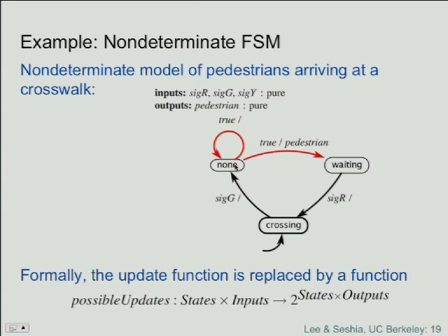Yes, question? So does that mean when you're in non-state, with no condition attached, it just stays yellow? Is that what's the question? Well, so I think what you're asking is how would we fix the design defect that we identified, right? Which is that if a pedestrian arrives while the light is yellow and pushes the button, this composition of state machines will not detect the arrival of that pedestrian and will not turn the light red. I'll leave it up to you as an exercise to figure out how to fix it. Okay, it's actually a good exercise.